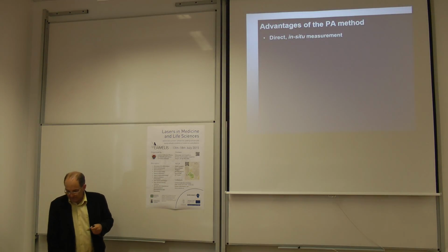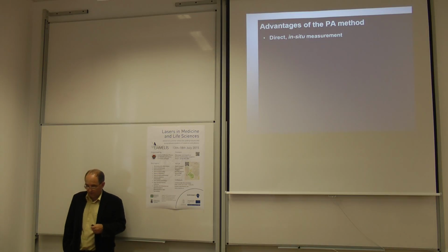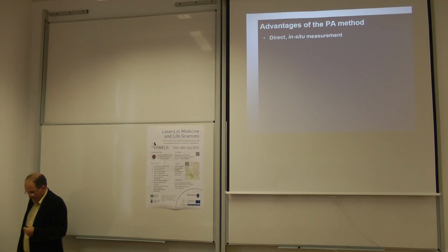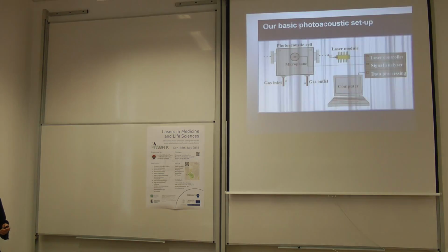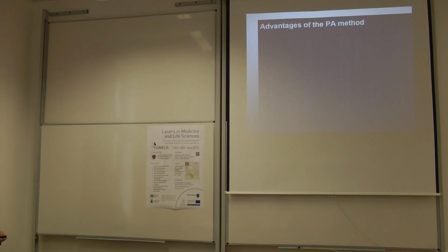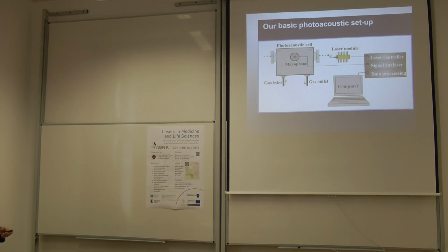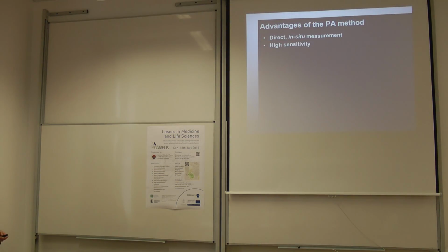So what are the advantages of the photoacoustic method? First of all, it's a direct in situ measurement. The gas to be detected is directly measured in the gaseous phase. There is no chemical reaction, there is no adsorption effect. It's a direct measurement of the molecules. Second, it has a high sensitivity. I will talk about it later.